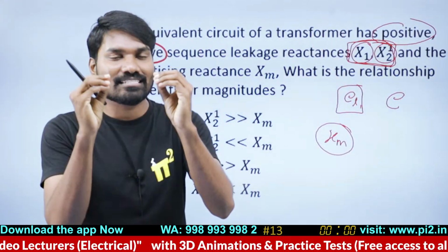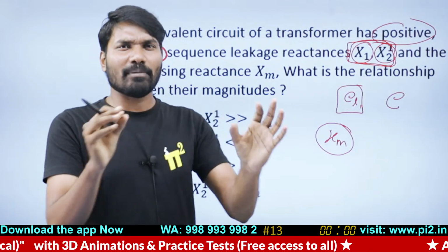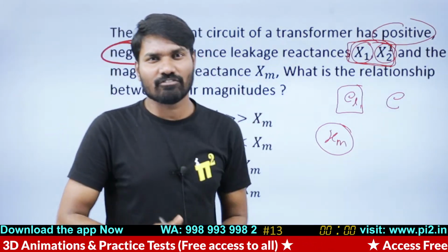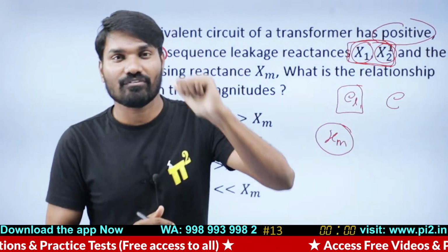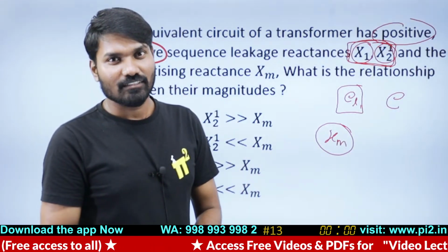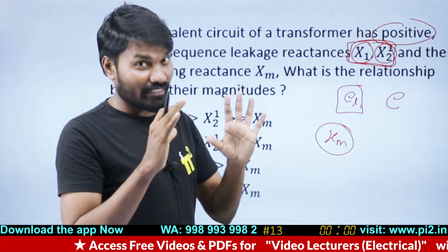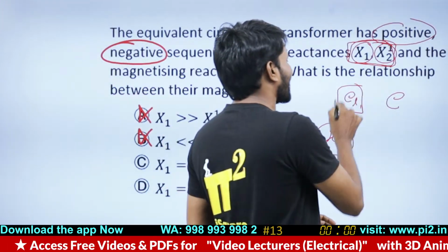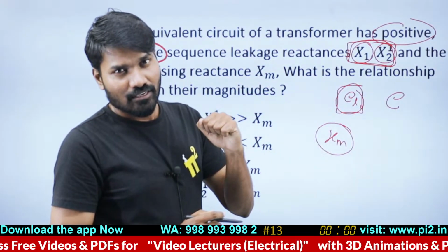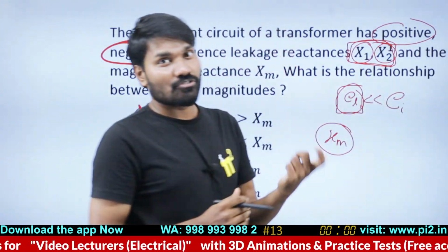To let you understand the concept, I roughly designed a transformer in the simplest way, within 5 rupees. So there the leakage EMF will be high compared to the induced EMF, but in a well-designed transformer, leakage reactance is very small compared to the actual induced EMF.